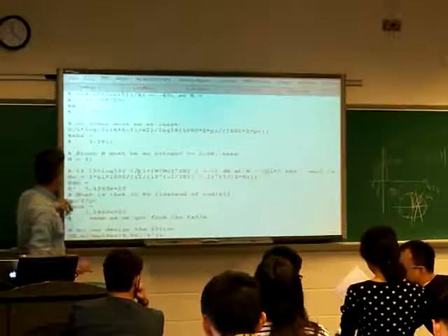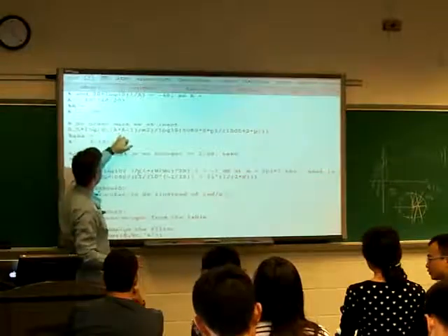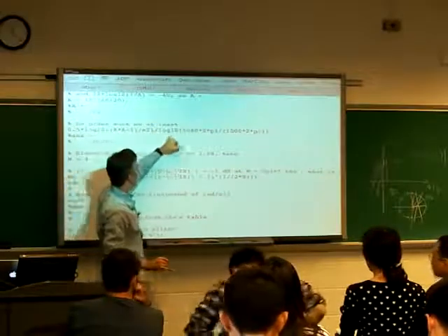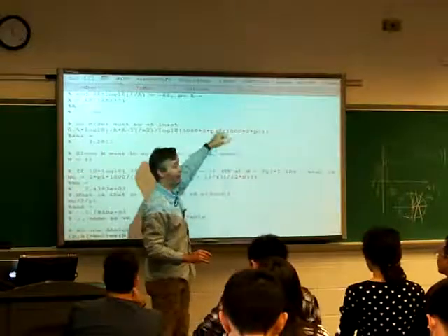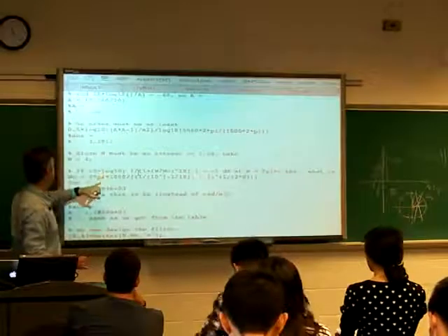And so then here's the actual design equation. So it's a half of log base 10 of A squared minus 1 on epsilon squared divided by log base 10 of the ratio of those frequencies. And that gives us this 3.28. So we choose n equal 4.